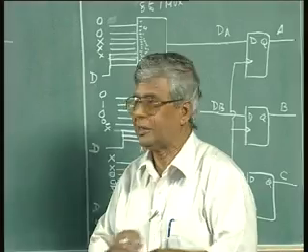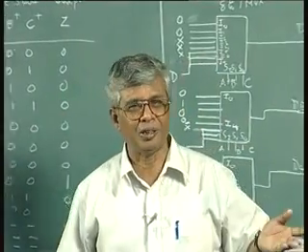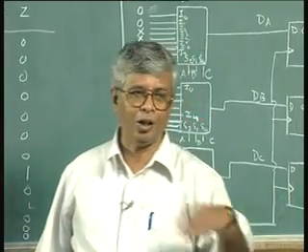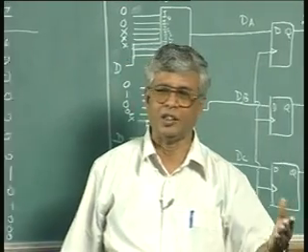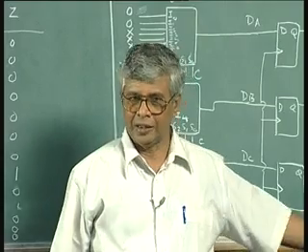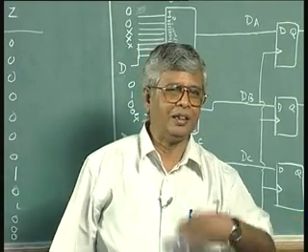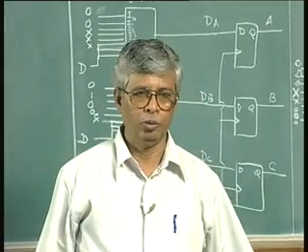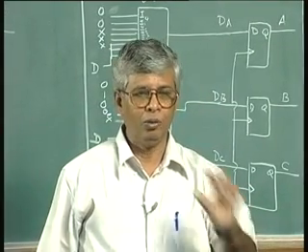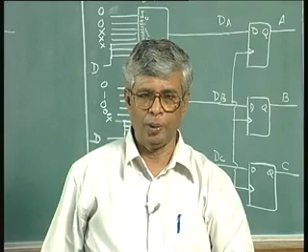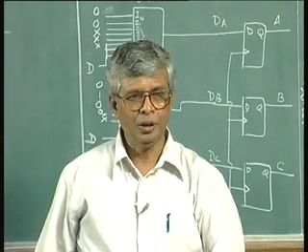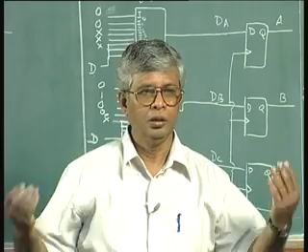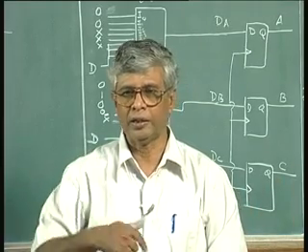So this is again an MSI based or LSI based implementation. Here, because the ROM size is too small, I don't want to call it an LSI. Usually ROMs and PLAs are classified as large scale integrated circuits, but the size here is so small. It doesn't matter actually, these definitions are not important. The implementation scheme is more important. How elegant it is: one chip ROM of appropriate size, program it, one register with 4 bits and a clock, that is it. Give X and output comes.